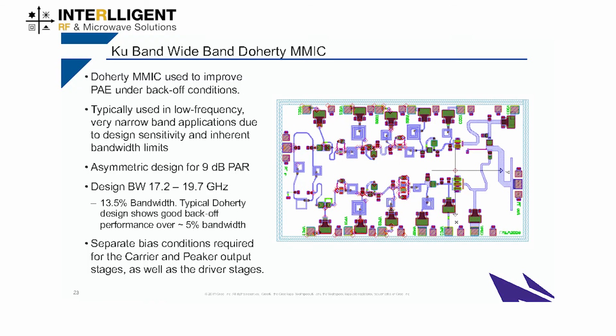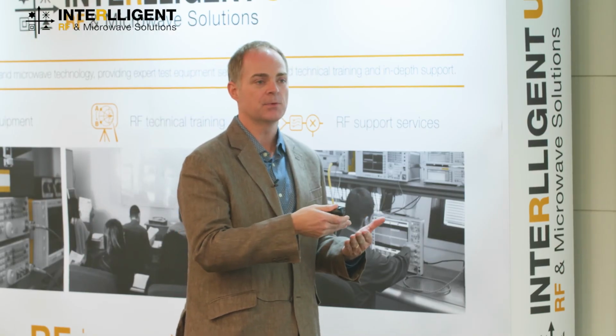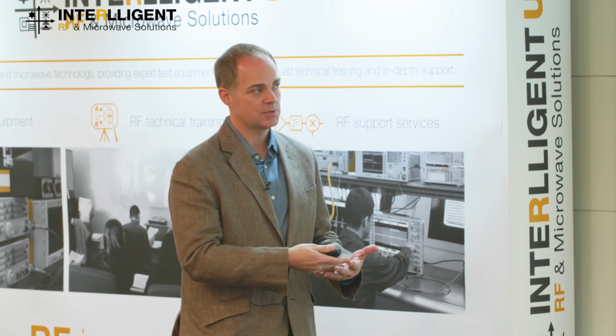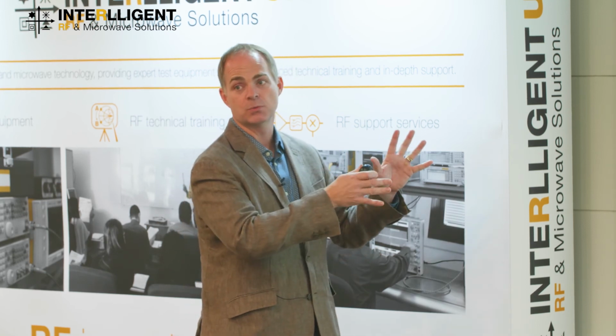So another application, this is a Ku band wideband Doherty MMIC. So typically, Doherty is used more often down at lower frequencies, and it's typically used in hybrid configurations, simply because the complexity of the circuit and the sensitivity of the circuit is very high. So putting it into a MMIC, you really need to have excellent models and an excellent understanding of the design in order to make sure that you're going to actually see the Doherty action in there, because once it's designed, there's no tuning it.